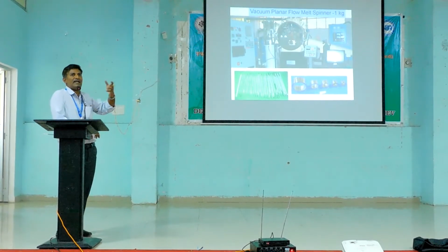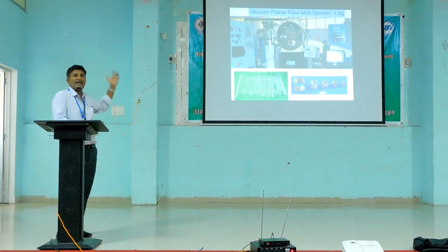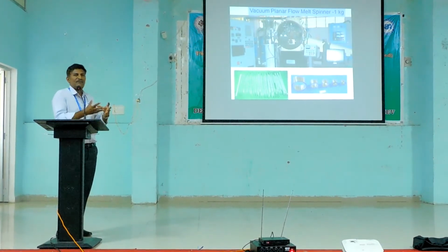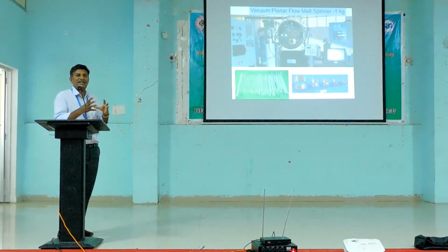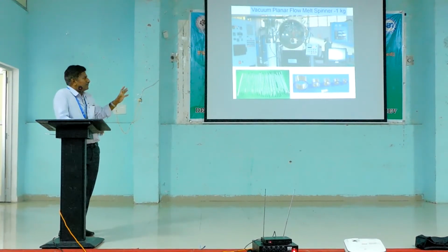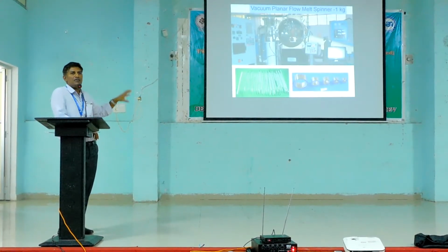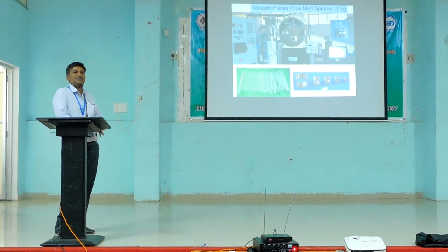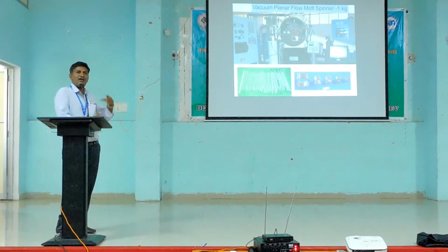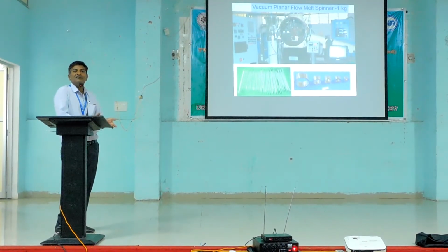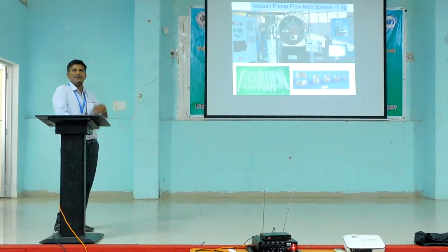There are some criteria. Like I was telling you, you need a high negative heat of mixing. It should be a eutectic system. The viscosity of the material should be increased so that it doesn't solidify quickly. So these are some ways by which we tailor make the composition. So making compositions, how to make an alloy, these are very big opportunities when you do research, choosing which element to choose, which elements to be replaced.